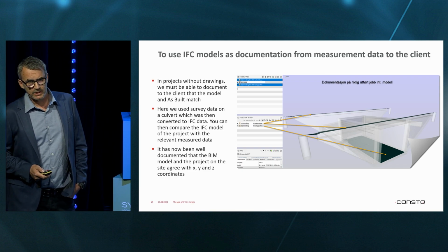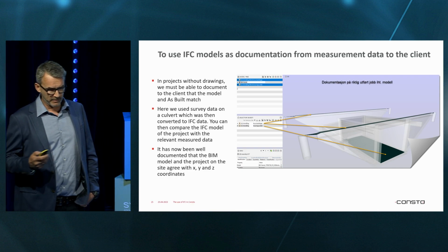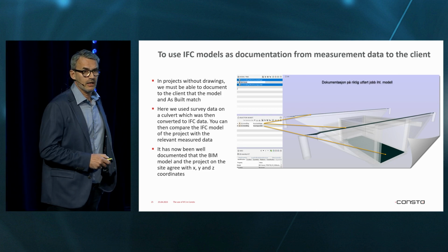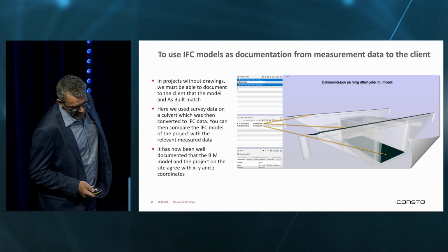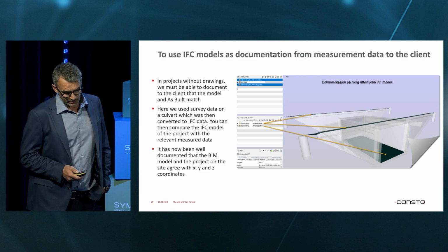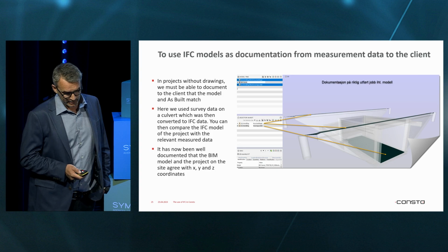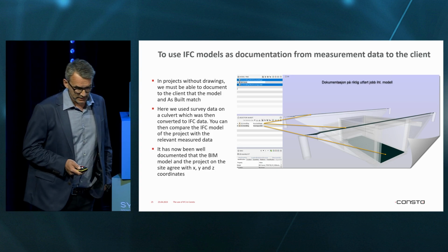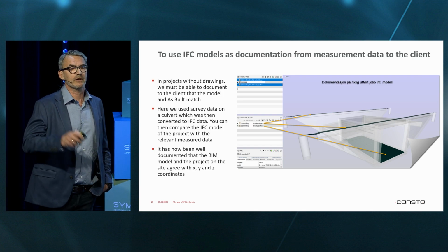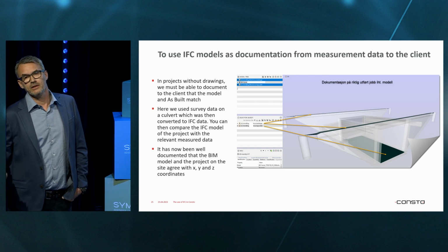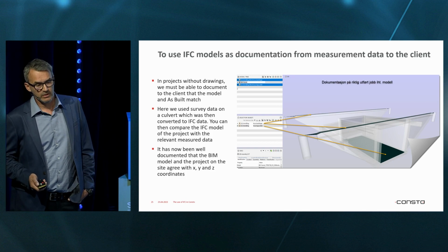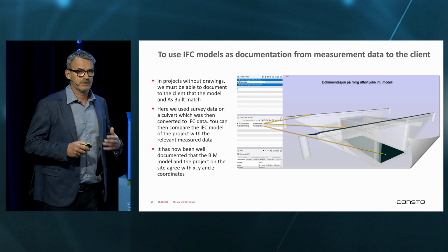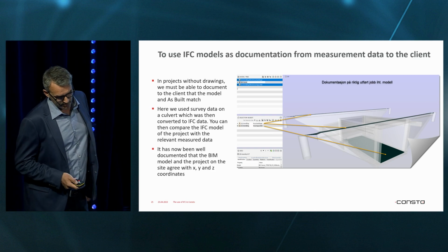Yes, and when we work with drawingless projects, we have to document the models, or we have to document what we're building against the IFC models. So in projects with drawings, we must be able to document to the client that the model and the as-built match. Here we use survey data, and we take the survey data, convert it to IFC, and compare it with the IFC BIM model. So the owner can actually check the correct stakeout data with the BIM model.